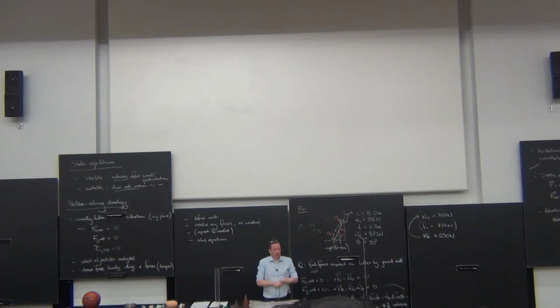So you've had a decent amount of practice with that. Hopefully at this point you're relatively comfortable with the calculations. Center of gravity is slightly different, but for our purposes, again, it is going to be the same point. It's simply a question of what is the center of an object, defined in such a way that gravity can be assumed to act solely at that point, and simply exert what can be seen as a translational force on the mass about that point, so there's no rotation about it. Equivalently, there's no net torque about that point either.